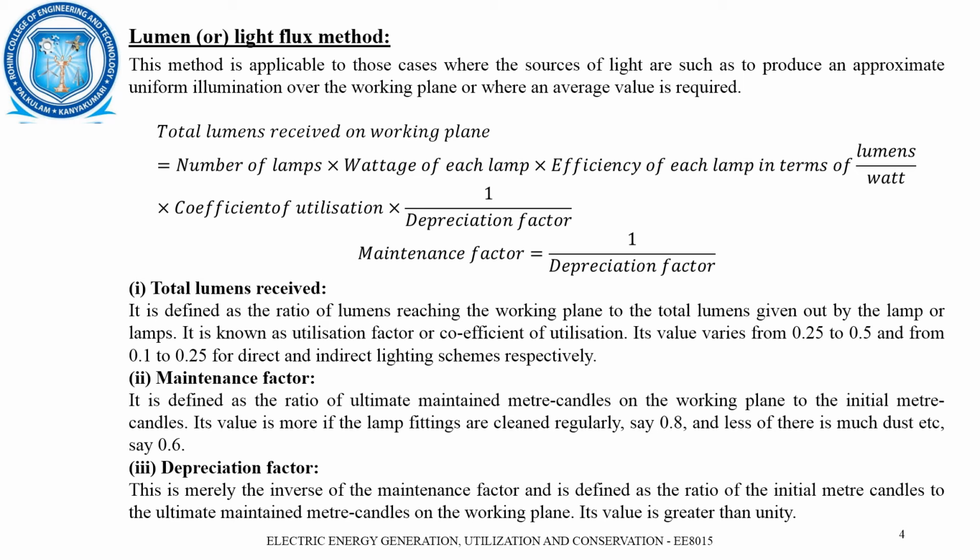Next, let us consider the depreciation factor. This is mainly the inverse of the maintenance factor and is defined as the ratio of initial meter candles to the ultimate maintained meter candles on the working plane. Its value is greater than unity.